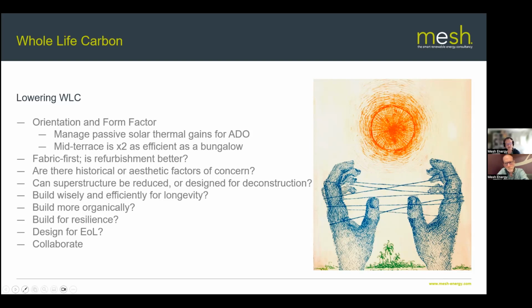That's quite an interesting concept, because the most common materials we'll hear about are polyurethane or PIR insulation, for example. We'll hear about mineral wool. But equally, in terms of thermal performance, when you're looking at mineral wool, then wood fiber insulation and hemp insulation have very similar thermal performance. And therefore, you can actually substitute these materials and start to reduce the global warming potential of your building.